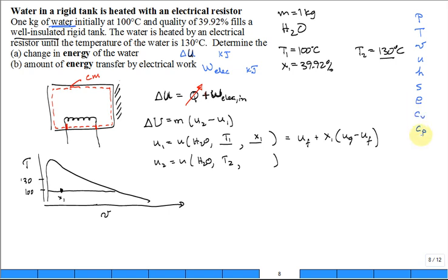These are all properties, I know, but we're getting down to the ones that are probably not relevant. K, the ratio of specific heats. There's a lot of other properties. Beta, we'll get to alpha, we'll get to other properties, okay? But those are the big ones, this top of the list, right? And think, do I know the pressure at state 2? Or could I easily calculate it? No. The temperature at state 2, bingo, got one of them. Specific volume at state 2, do I know it or is it easily calculated?